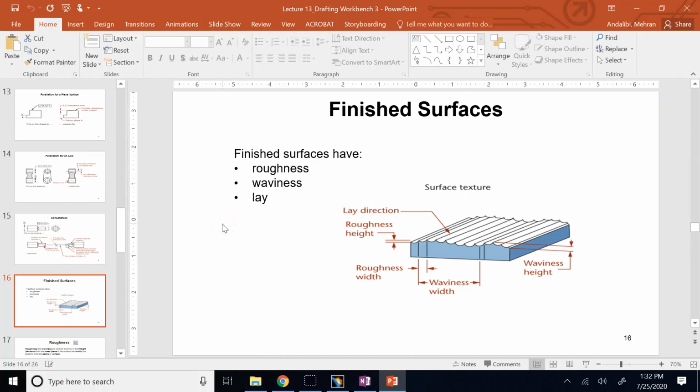Two more other things that we touch. One of them is called surface finish or surface roughness. Whenever you create parts, for many applications, the smoothness of the top surface, or the surfaces that sit on top of each other, does matter. If the surfaces that sit on top of each other are too rough, then there might be some holes and gaps between them, and those might not keep, let's say, the compression that you want.